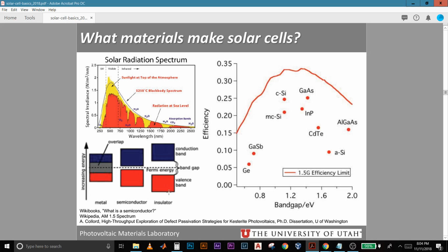If we look at insulators, there is a large energy gap, and in semiconductors, it's in between these two. Now, if we have a material with a band gap which is equal to the energy of a photon, then it can absorb that photon and cause a state transition of electrons from the valence band to the conduction band, thereby giving rise to electric current.